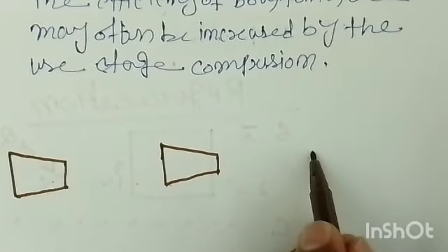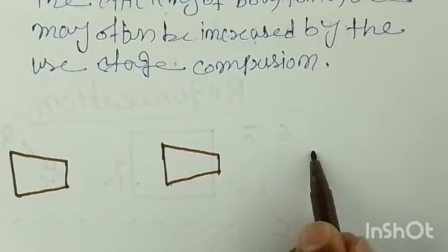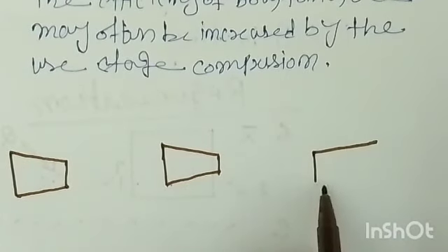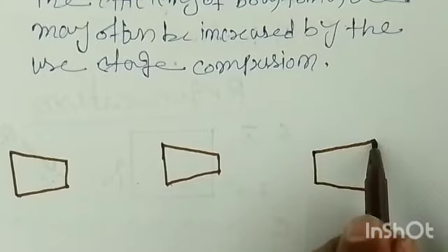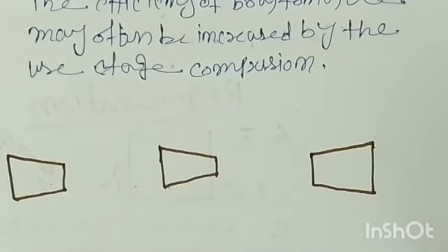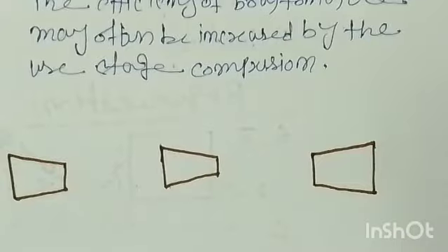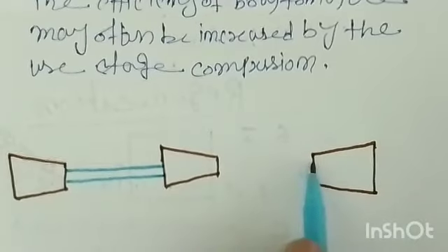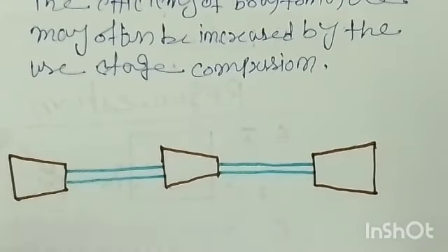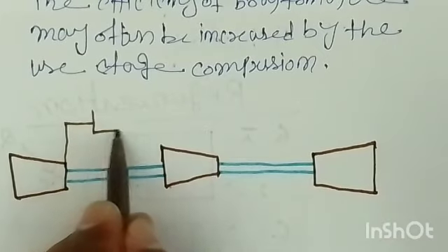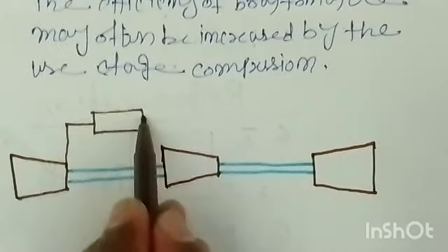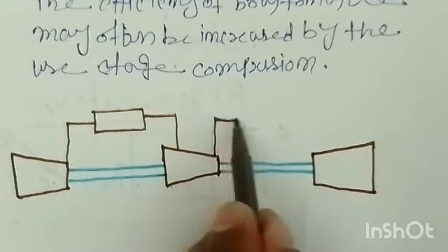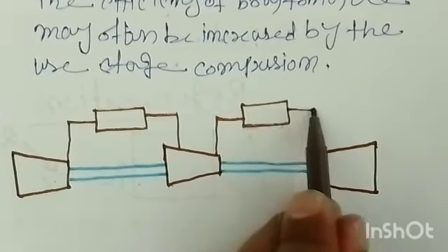With this we will add one turbine here itself. So this is your gas turbine. Then we will couple them so that we supply the work we are getting from the turbine. Now, we have two combustion chambers; first we have to use the intercooler here. This is the intercooler, and in between we have one combustion chamber.